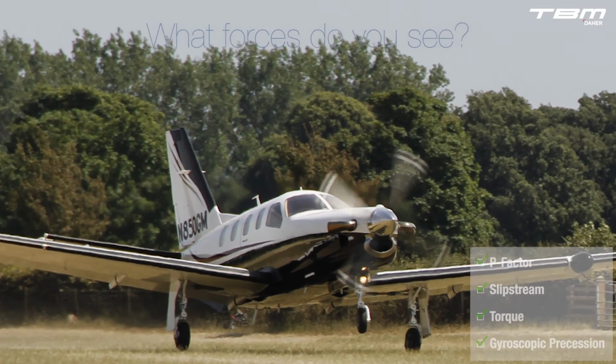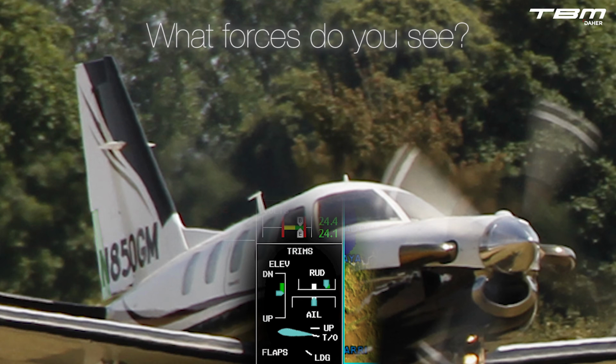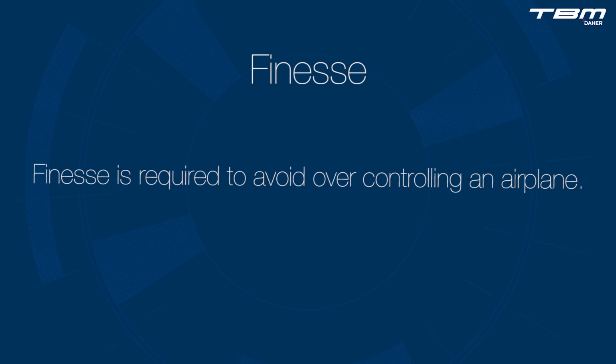The left turning tendencies induced by propeller are real and well pronounced at low airspeeds. Proper use of trim settings during takeoff reduces the control forces required to maintain aircraft control. As an airplane slows below reference approach speed, less than 1.3 VSO, the ailerons become less efficient. However, the rudder's secondary effect, contributing to roll control, becomes primary. Finesse is required to avoid over-controlling an airplane.